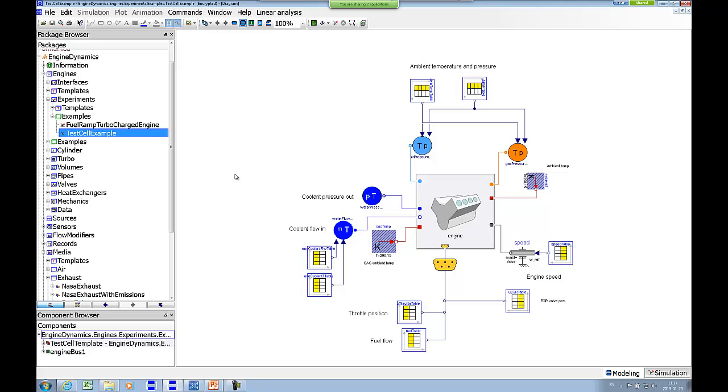That could be either table-based, and we have actually added an equation-based compressor map model with 1.1 that handles better extrapolation to low rotational speeds, which is often a problem with tabulated values, that they do not cover the low speed operating points in the engine.